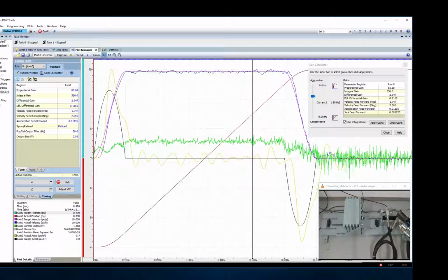Well, first thing is that if you're a controls person and the hydraulic designer designed the system wrong, if there's any chance of tuning it correctly, it's going to be with using the second derivative gain, the advanced control system. The other thing is if you're a designer and you want to save a little money, you can reduce the natural frequency of the system down to only about 2 times the frequency of acceleration and still be safe. You still get excellent control.